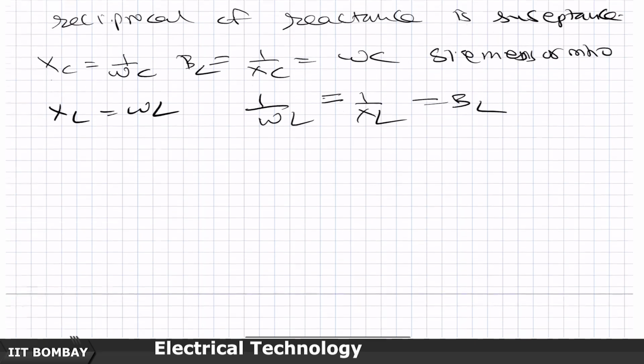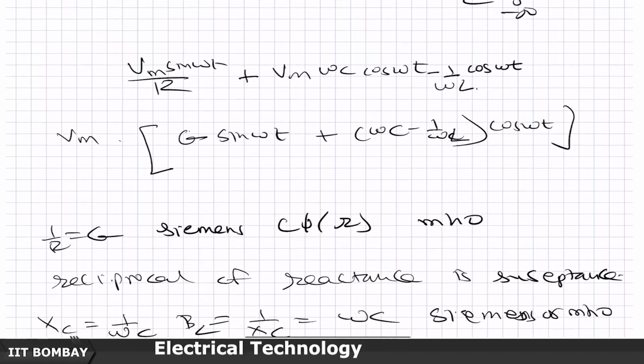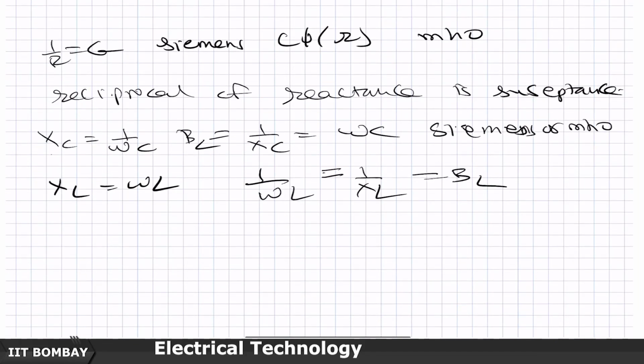Now, if you look at it, when I have a parallel circuit, say a resistive circuit, 3 resistors in parallel, and I ask you what is the net resistance, what do you say? You take the reciprocal of each of the resistances, add all three of them, then take the reciprocal. So 1 by R equivalent will be 1 by R1 plus 1 by R2 plus 1 by R3, and whatever you add is the reciprocal of the net resistance. Then you get the net resistance from here.